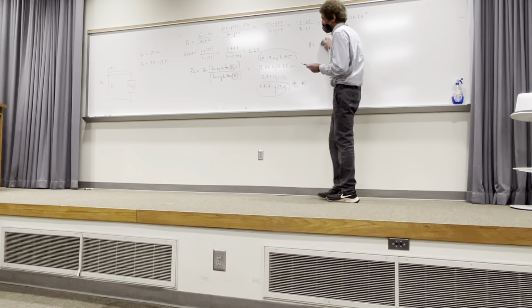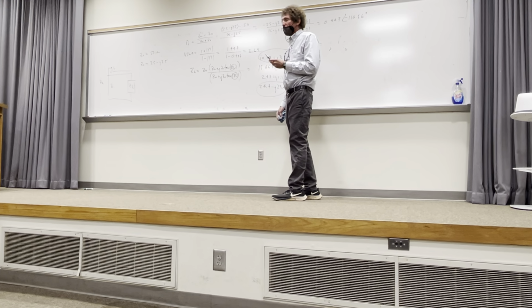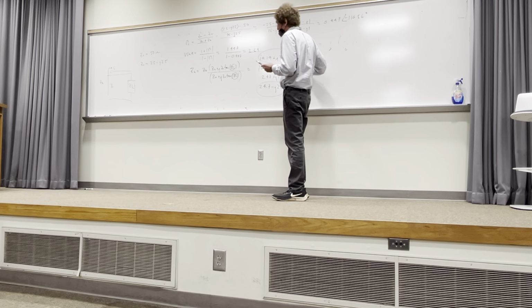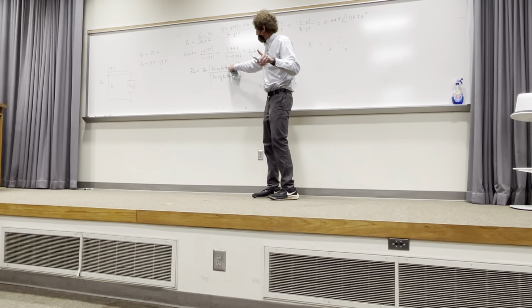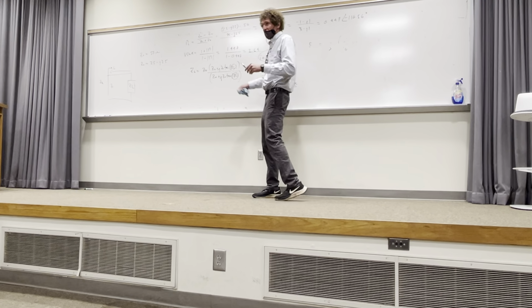Out of curiosity, we have this. If I gave you an input voltage, y'all know how to find the voltage at the load there? Remember the complete circuit we did? You've got to make sure you know that kind of stuff. But remember, for that problem, this is the thing that gives you your input impedance that you do voltage division with, right? So if this isn't right, everything else is wrong.